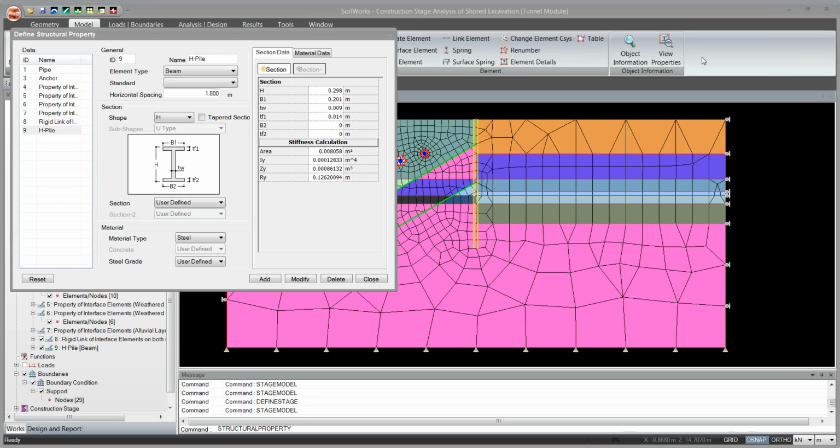Okay, perfect. And talking about the lagging again, since I said that it's a 2D model, the lagging will not be modeled. But what we can do is, this is the cross section at the location of a pile, but if you want to take into account the lagging, you can model a cross section where the pile is not present and then obtain the results for the same. But since it's not a 3D model, you cannot model the lagging. I hope I answered your question, Juraz, but we can talk more about it if you want.